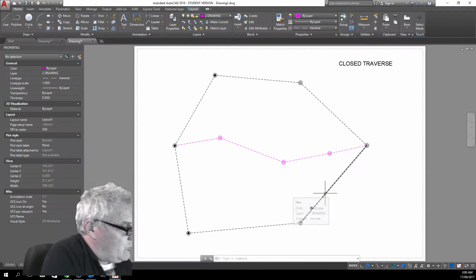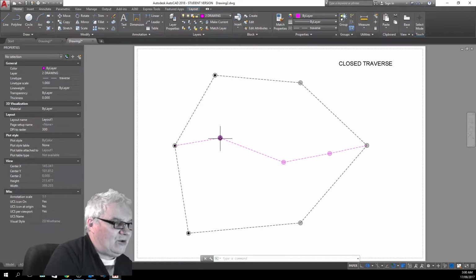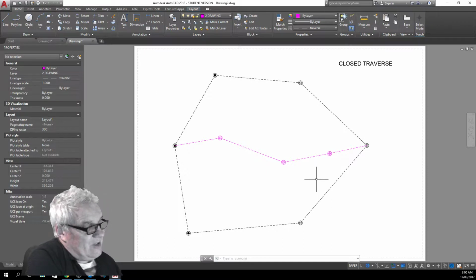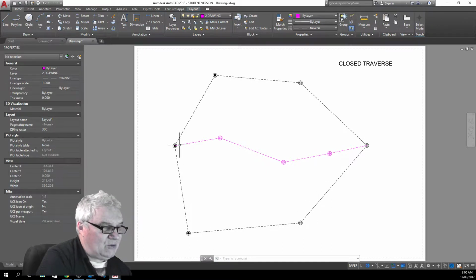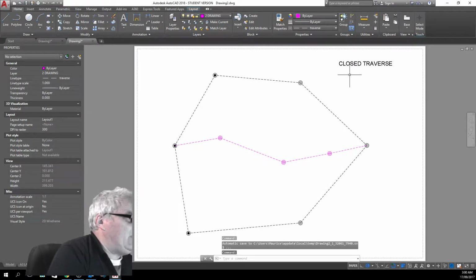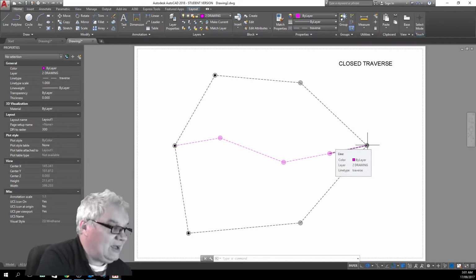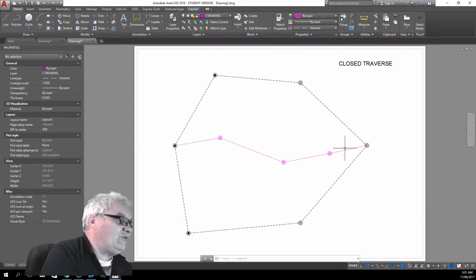Now if we don't, then what we do is we adjust out any error into these new angles here, and we adjust that out. It's sort of as if we had all this other stuff around here, but we don't use that. We just do it on the bearings, and so that there is called a loop traverse, because it loops from one set of information to the other.